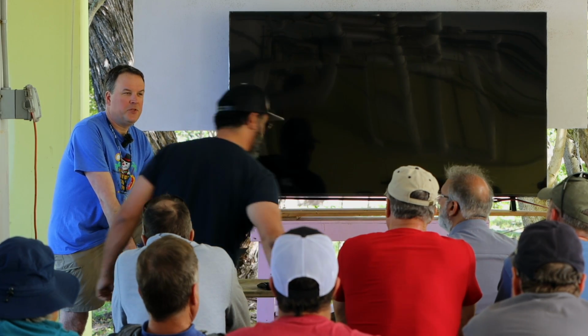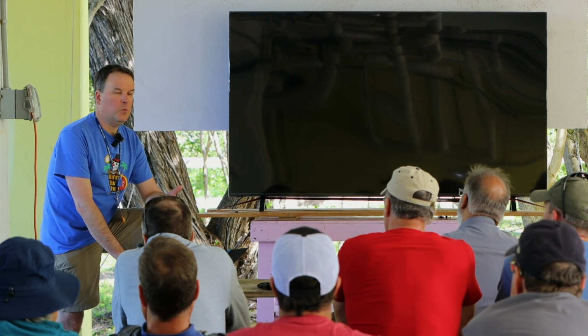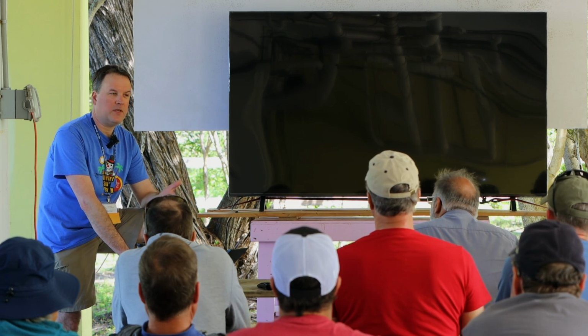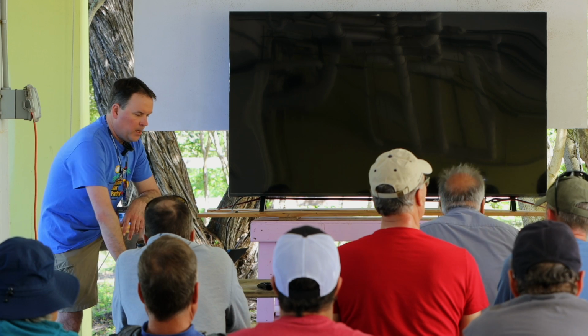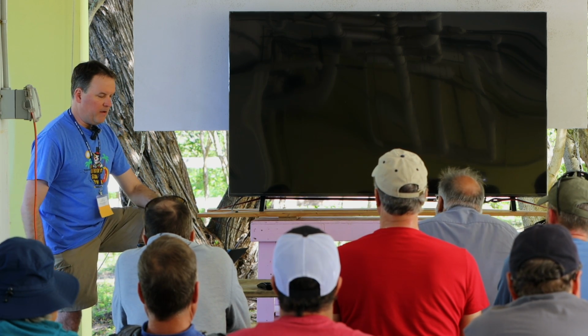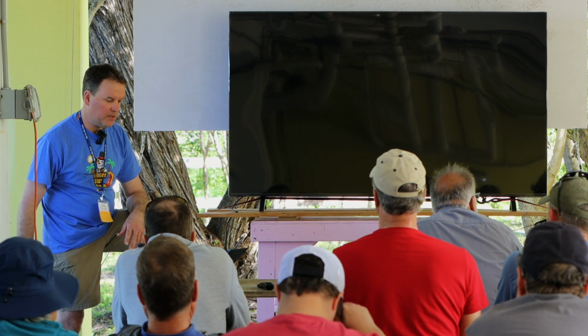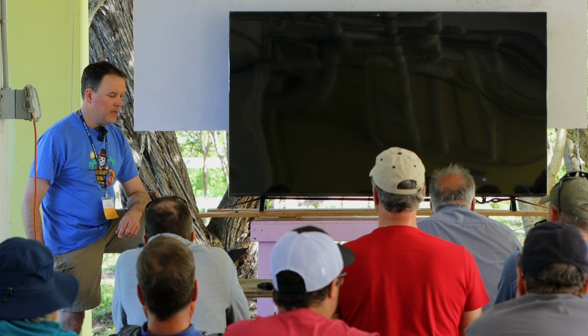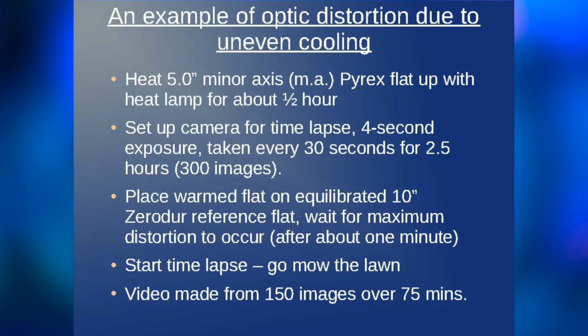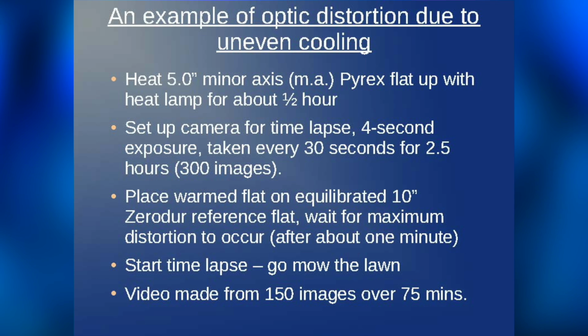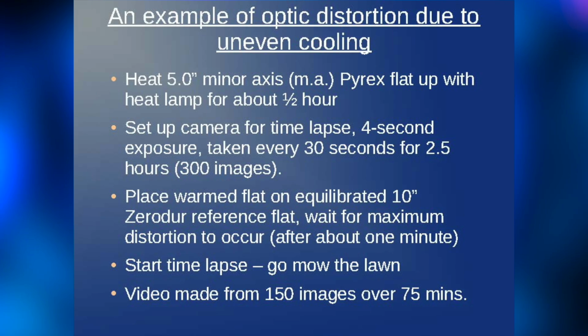And so the imagers know this well, and some of the better imaging telescopes will be designed to be athermal, or they have focus compensation for temperature. If we're doing steel, we have a change in dimension for the steel, 50 inches long, roughly of about 9 thousandths of an inch, so the difference is about 7 thousandths. Invar is about 1 thousandth, so maybe 1.7 thousandths of an inch difference as this thing cools off 30 degrees. And Zerodur and carbon fiber, let's say, there's almost no change at all. So ideally, if we could have that for everything, that'd be wonderful.